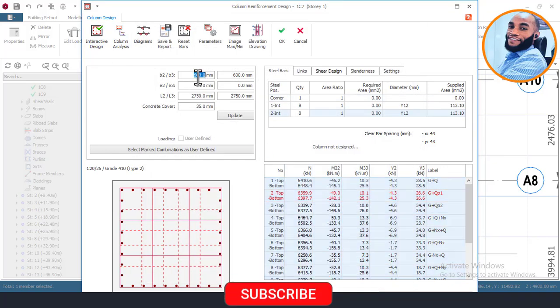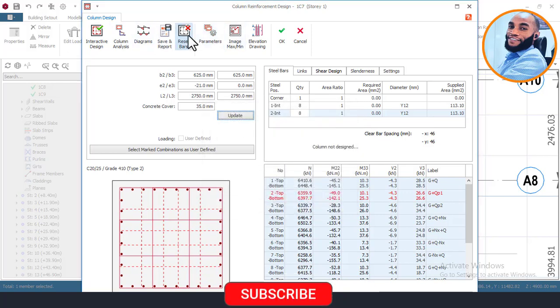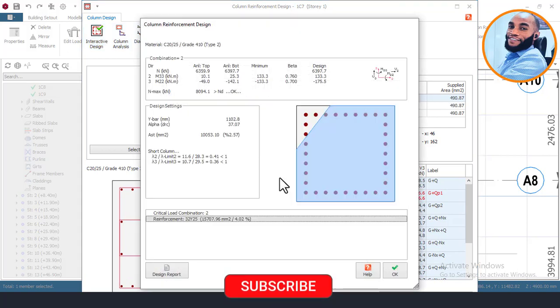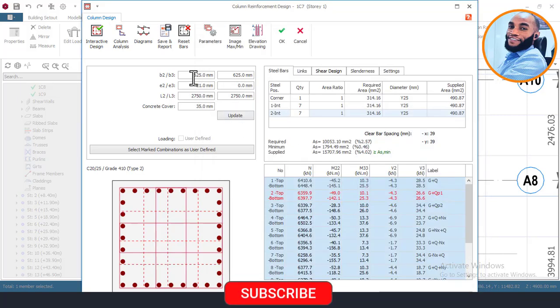So I'll come here right now and choose back to 650. I can quickly try 625 and then update, and then come here, choose back this default method, and reset bars and then design and all that. Let me see. So you can see that basically 625 is okay to carry the load imposed on that column, but we are having 32 number of Y25. So I think that just to have uniform column sizes, which I've been using, 650 before, I'll just maintain 650 and all that, and also to help reduce the number of bars that was showing 32 to at least 28, I think so.